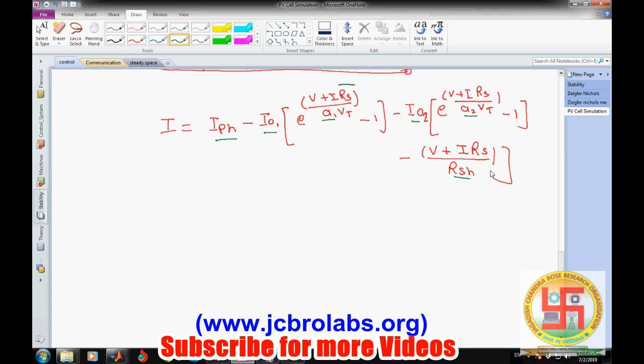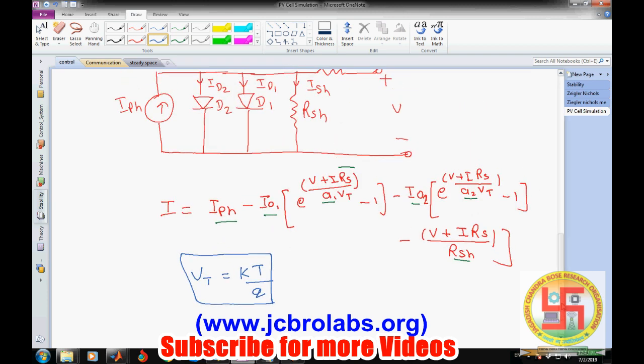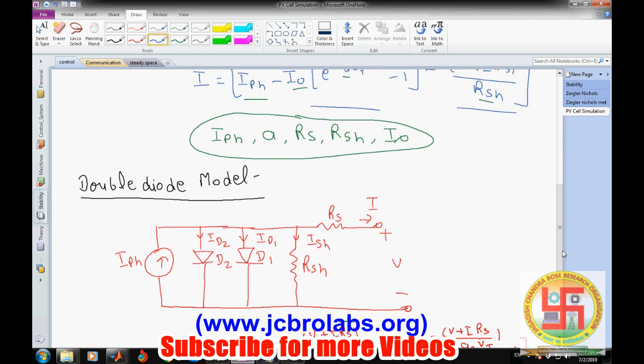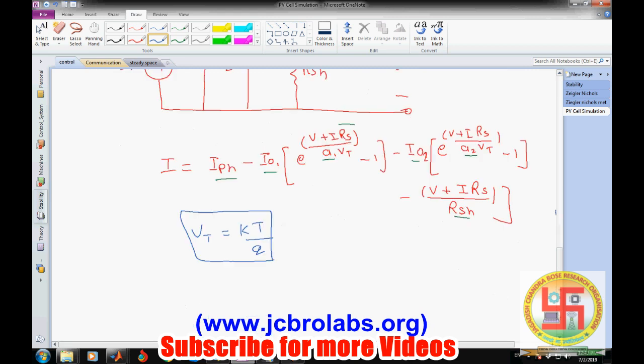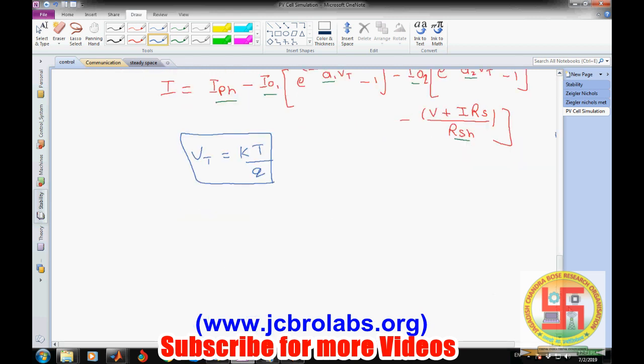Now, which I forgot to mention here, VT is the thermal voltage, which is given by KT by Q. So this diode voltage is obviously temperature dependent, which is the terminal voltage of the diode, given by KT by Q. These are the basic equations of the solar cell, which you should know as the basics of it.